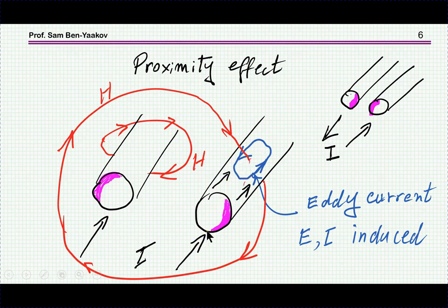So as a result, we're going to see that the charge carriers, electrons in the case of a metal, are pushed into this side, and the same thing, of course, will go to the other wire. So we are going to have a situation in which only part of the wire diameter is actually being used, so the equivalent resistance, the so-called RAC, is much larger.